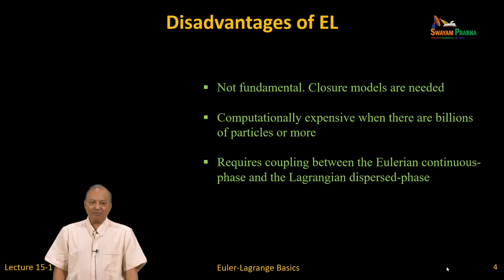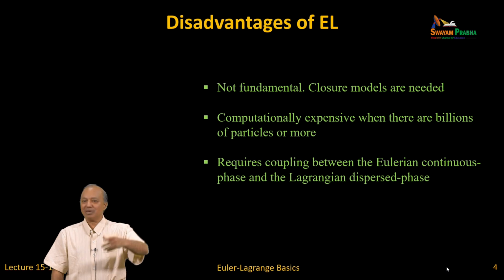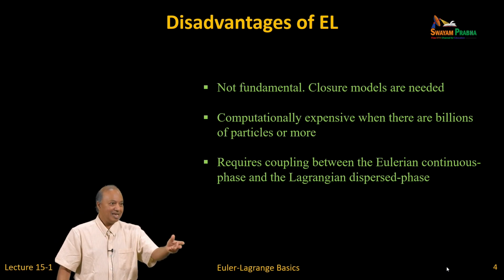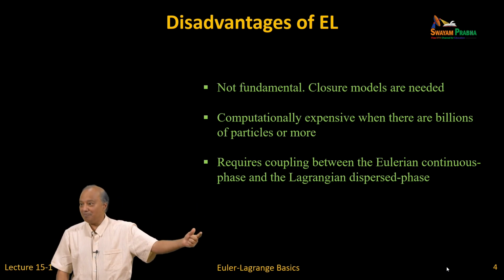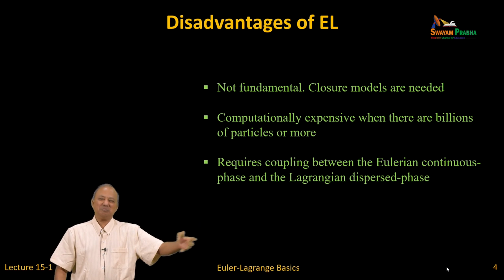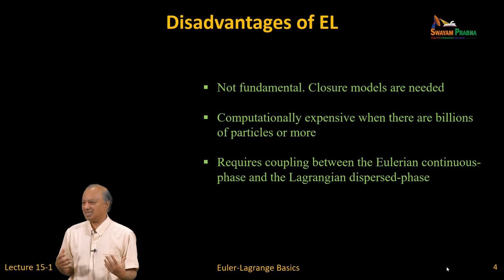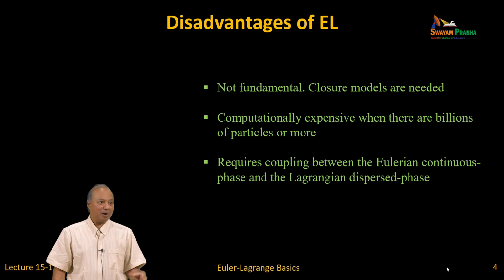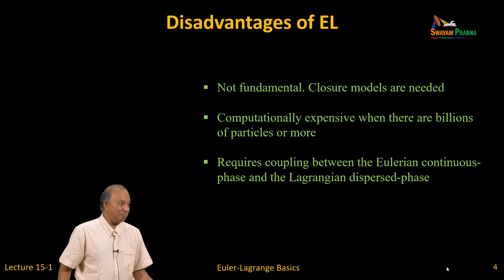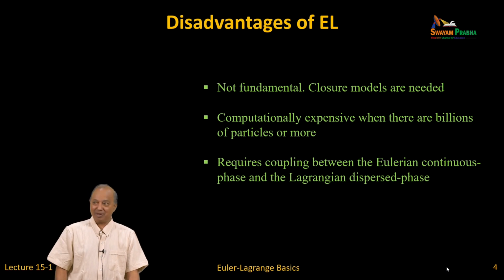Change of your fluid velocity there is due to advection plus diffusion plus pressure effects, right? Now, on top of it you have feedback force, that is an additional term. If that added term is not that big, even if it is fluctuating, it is not that big a deal. If that added term is big, if the particle's feedback force is very big compared to your advection and diffusion, it is going to change the fluid mechanics.